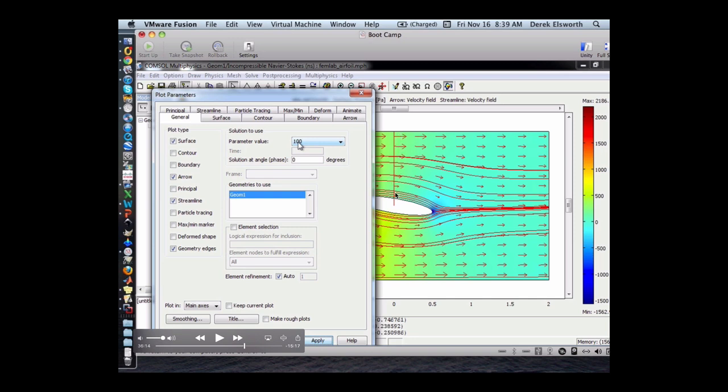The reason for this is because it's kind of confined flow. It's like flow in a box. So you can imagine this is a box. So now all the flow that has to go past this airfoil is squeezed into a cross-sectional area which is less than its full height. It's 1 all along here, but has to speed up here because it's constricted. So that's the reason it's 1.6.